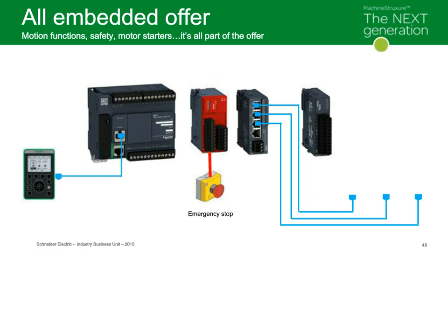In addition, what we did with one of the I/O modules is we added a TeSys motor starter interface. So with one simple RJ45 connection, you're able to connect to your TeSys motor starters and be able to run, stop, forward, reverse, jog, get the information back with that one connection and translate that back to your PLC.